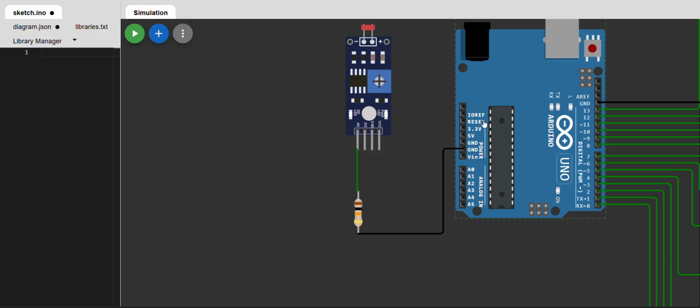of Arduino. Next, I have taken the output from the analog pin A0. I have taken the input to the Arduino from the LDR, and I have connected that particular pin to A0 of Arduino. Next, I am going to connect the ground terminal of LDR to the ground terminal of Arduino. I am going to connect VCC to 5 volts.